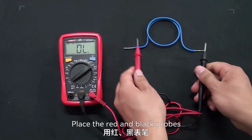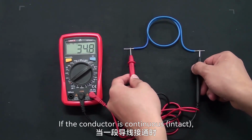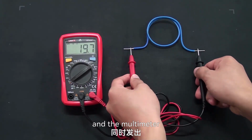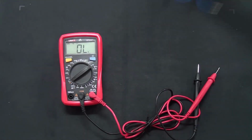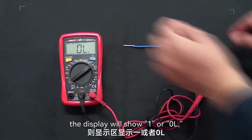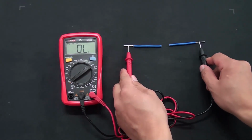Place the red and black probes at both ends of the conductor. If the conductor is continuous and intact, the display will show the resistance value of the conductor, and the multimeter will emit a beeping sound. If the conductor is broken, the display will show 1 or 0L, and the multimeter will remain silent.